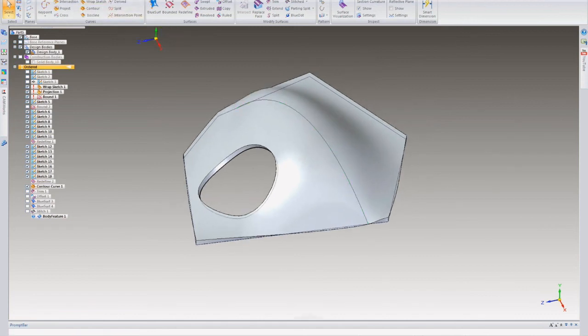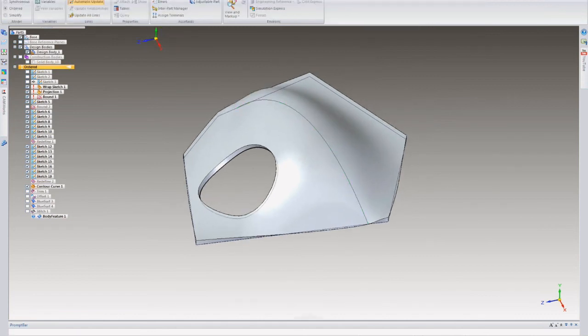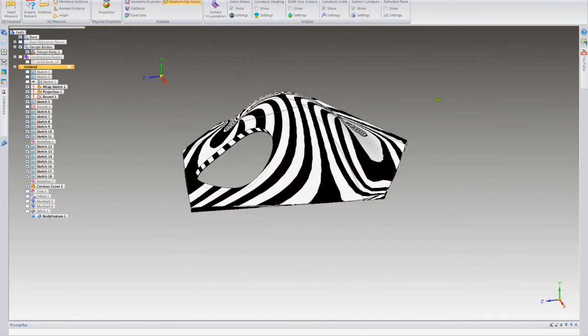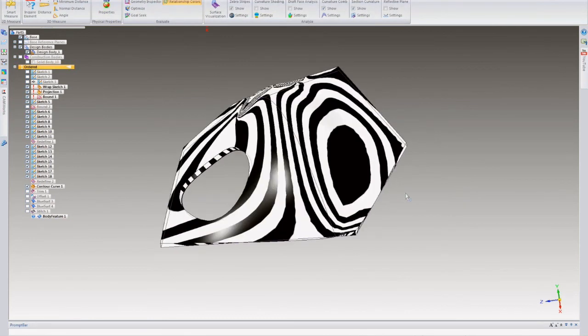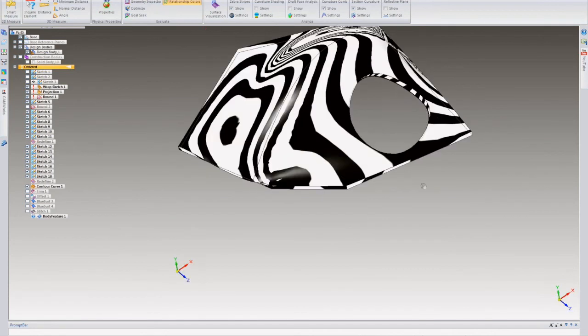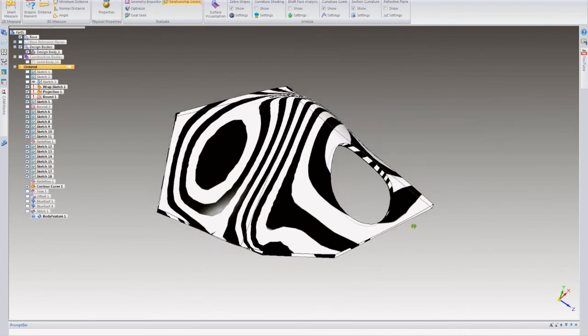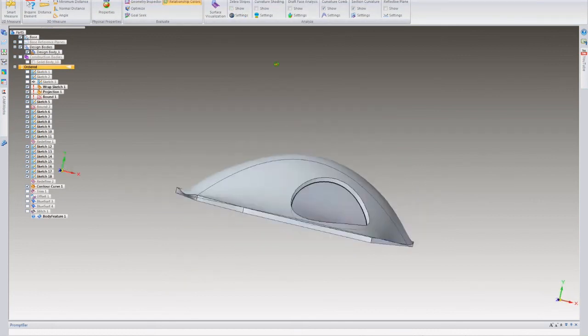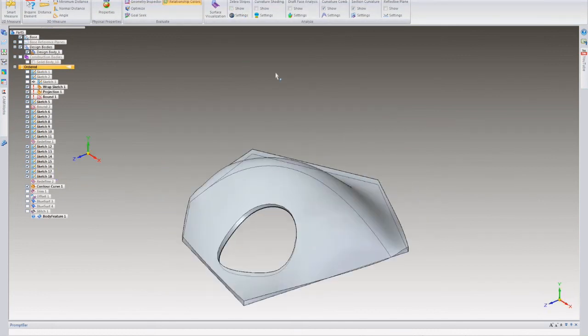All right, so after you're all done, if you ever wanted to inspect your geometry to show the curvatures, to see how tight and how close, as you can see on this side, the surfaces wrap across there fairly nicely. So we get nice continuity between the profiles using BlueSurf. It gives you the G2 style of continuity for your surfaces.